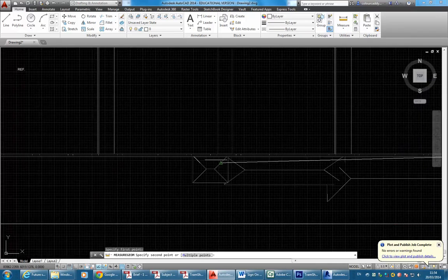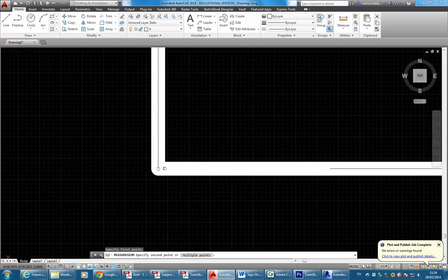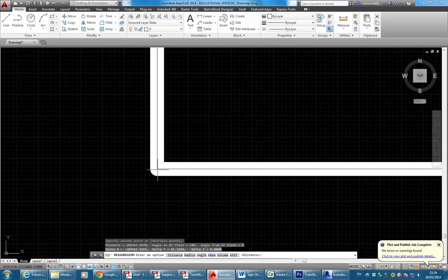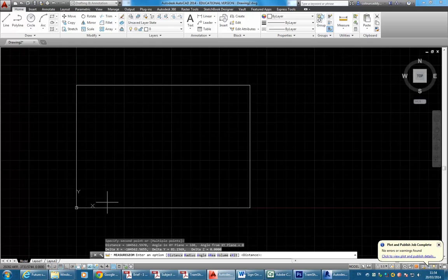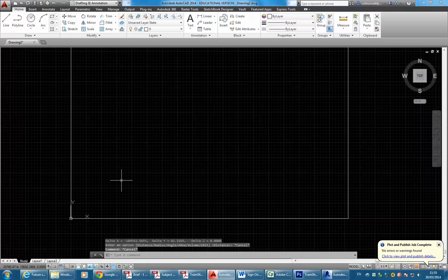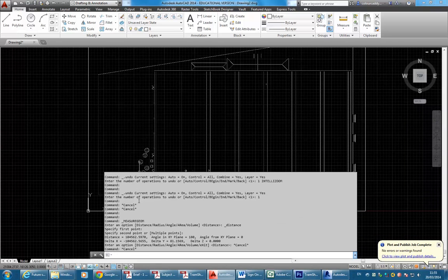Okay, so with the satellite image you could tell the size in properties, but in this case I want the size just of one part of the drawing. So I've measured across, clicking 2 points, and you can see there the distance 104,562 is actually the size that it should be. And that's another thing that can happen with PDFs. When you get a PDF that's been made from AutoCAD, chances are when you take it back it will be the right size. Yeah. So if you're lucky, that's what will happen.